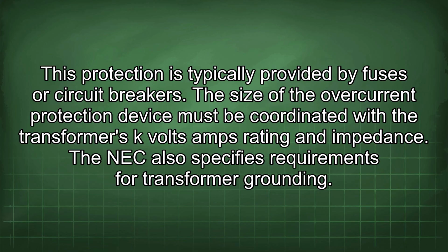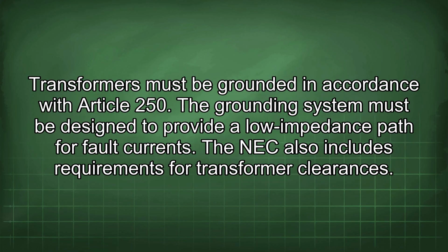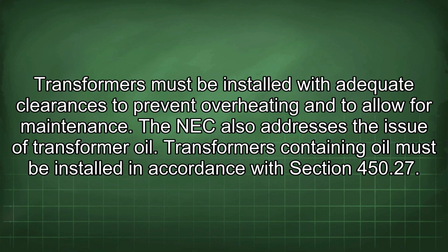The NEC also specifies requirements for transformer grounding. Transformers must be grounded in accordance with Article 250. The grounding system must be designed to provide a low impedance path for fault currents. The NEC also includes requirements for transformer clearances. Transformers must be installed with adequate clearances to prevent overheating and to allow for maintenance.